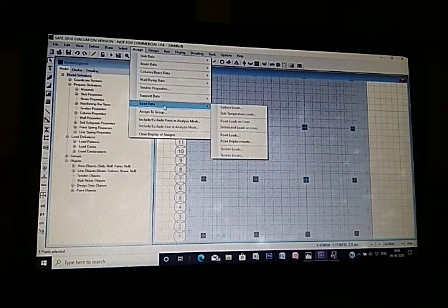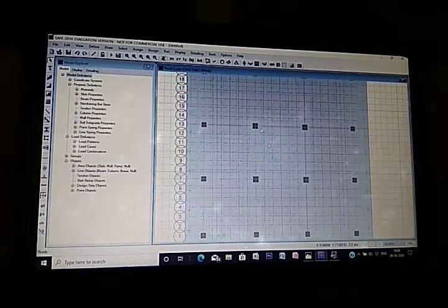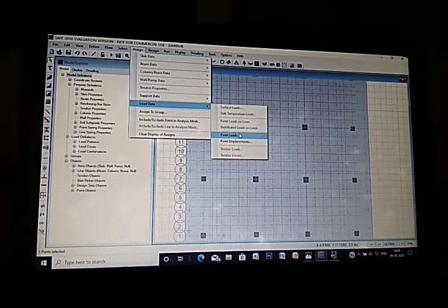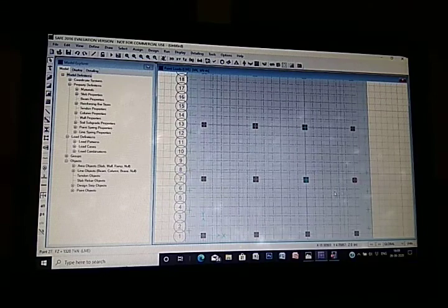So it's column 7 dead load. Column 7 dead load has 4977.2 of size 600 into 600, and live load of 2579.8. Similarly for column 9, now it is column 10 and 11.